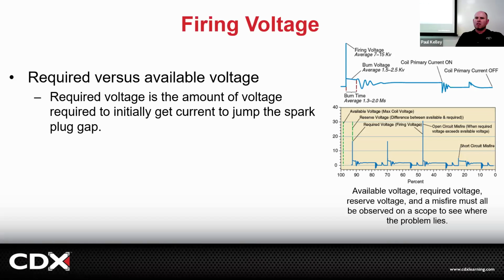Typically, if it's a fuel issue, it's more like a consistent loss of power, whereas if it's one coil on a coil-on-plug system, it'd be more like a misfire. But if it's a car that has one coil for all the cylinders, the ignition coil failing will be sluggish and the fuel will be sluggish too, and it's hard to tell which is which, to be honest. So driving it a lot of times is not enough to determine. You're going to have to take some measurements and do some actual diagnosis.